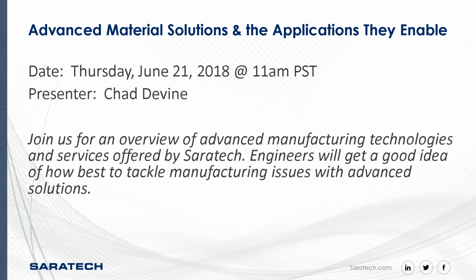Sure. So his question is, can additive manufacturing technology be used to produce parts at large production quantities like MIM process? So I would probably say for the Metal X technology, probably not. It's more of a prototyping, I would say 10 to 500 part scale production process. It's to hit the market right in between what you can't achieve with traditional MIM technology, right? So it's not something to replace MIM, it's something to advance the process of MIM.